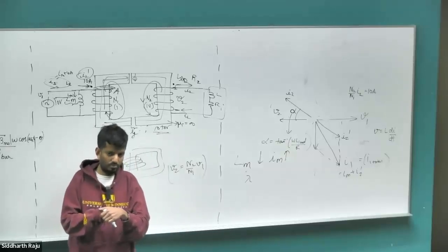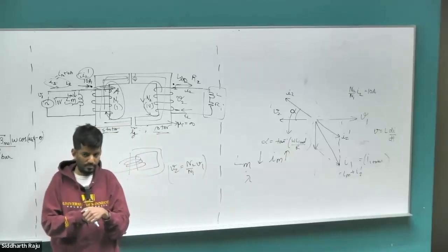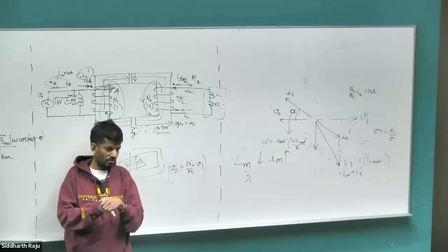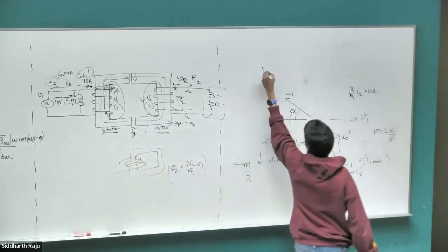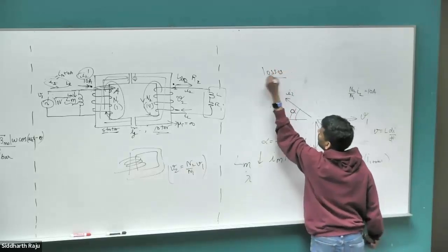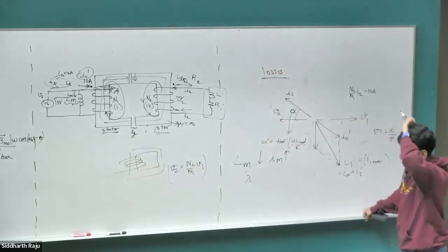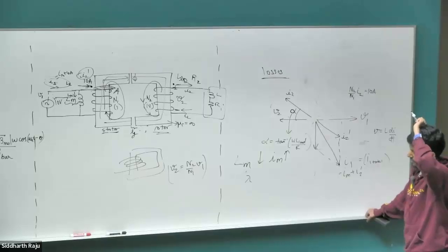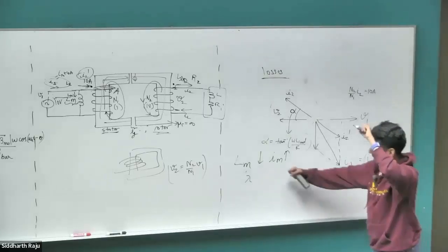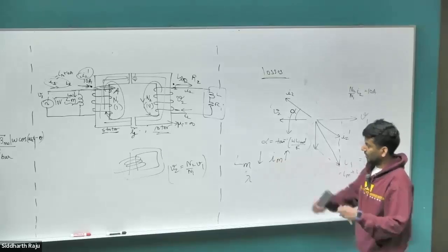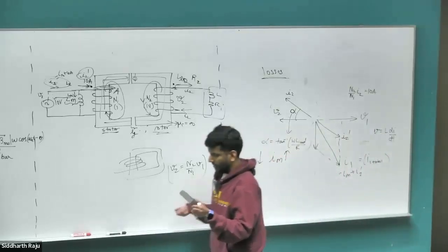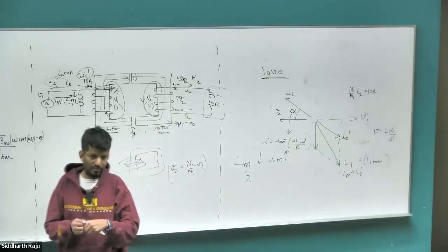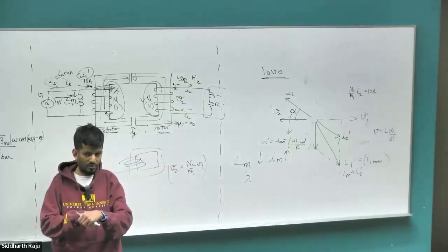Losses? Losses, perfect. Another answer? Losses is the primary concern when you have a drive connected induction motor, because you still need higher current to establish the same flux, which is then going to lead to higher I squared R losses. But let's say induction motor, typically the advantage is you can directly line connect the induction motor. For a grid connected induction motor, what's the problem?